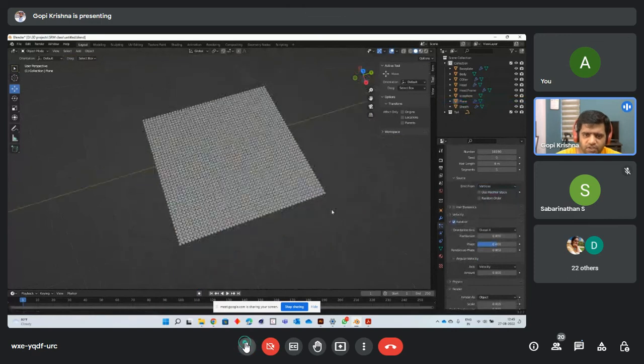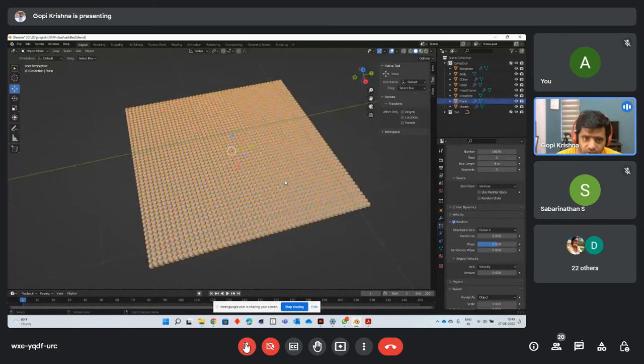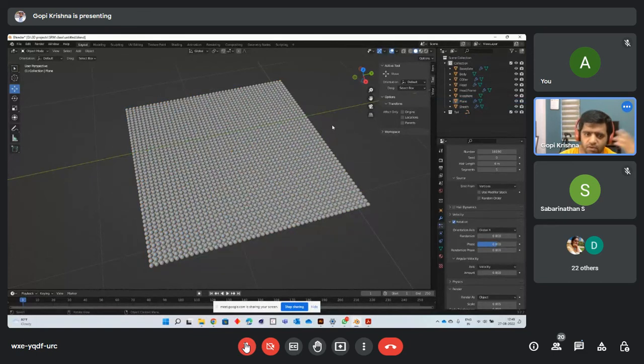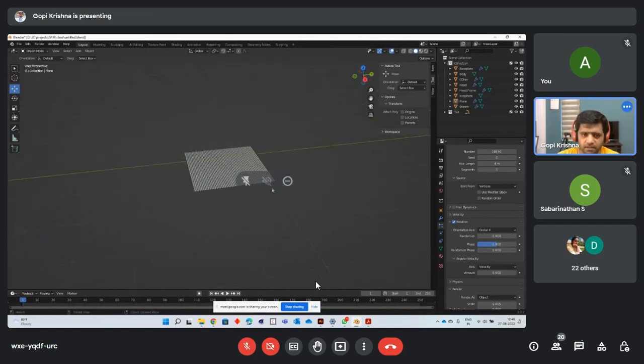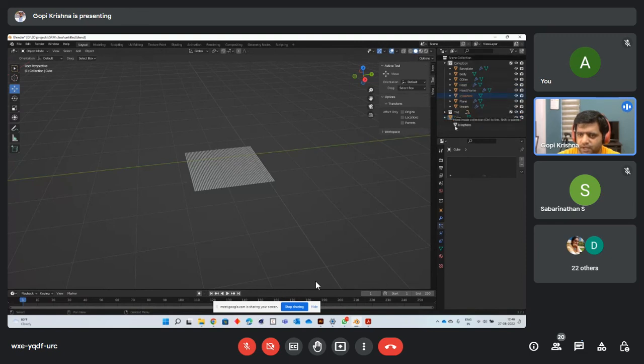So this shows the usefulness of vertices in the particle systems. It's very useful if you want to distribute a similar object to a lot of places. Actually, you can distribute more than one object at the same time. If you have one cube, for example, I'll add another cube first. Get a mesh and a cube. I don't know where that's going to create it, but it's fine. So I'll keep the cylinder and cube inside one collection called particles. It doesn't matter what the name is.